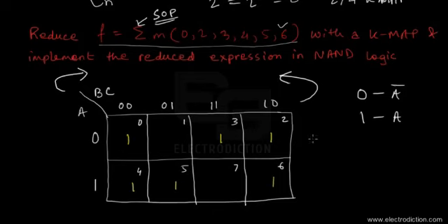So with that kept in mind, we can group up the cells 0, 4 on one hand. I'll use a different color over here. We can group up the cells 0, 4, and then 2 and 6 together to form a quad. Now on the other hand, we have the cells 3 and 5 that remain.